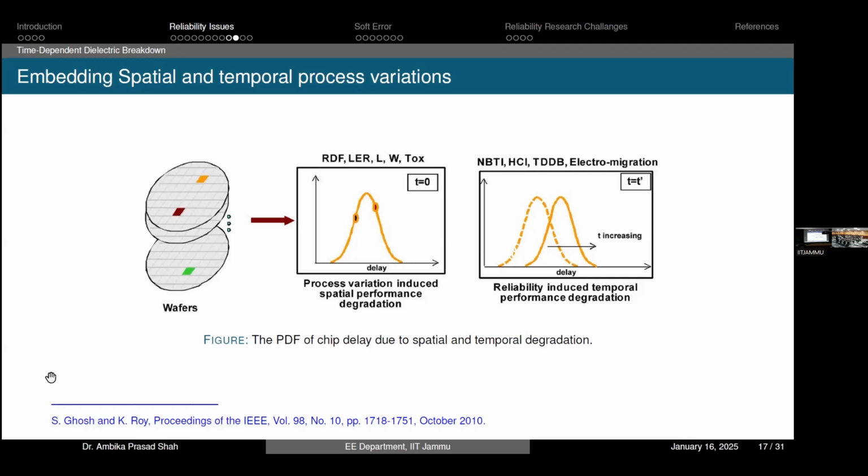Left side does not matter. On the right, less delay is fine, no problem. But if you see the right side one, the delay on the right side is higher than whatever limit you have. And for those ranges, your system will fail. They will not work because they are not meeting your specifications. So what you need is less process variation.